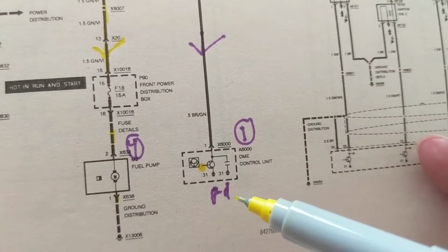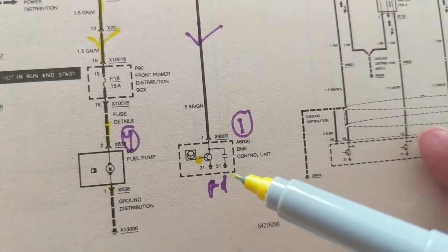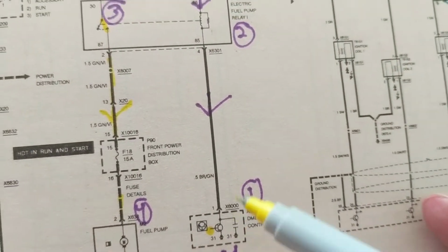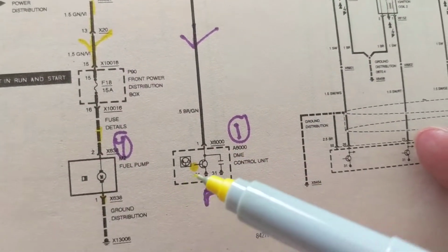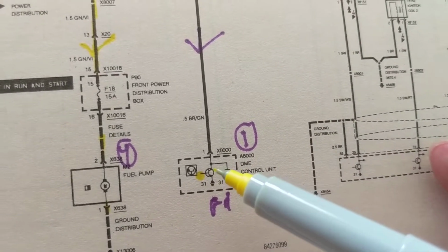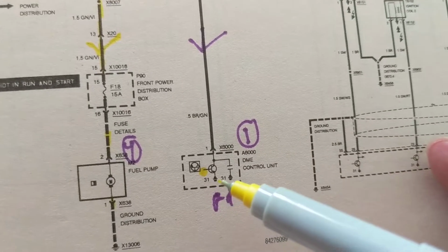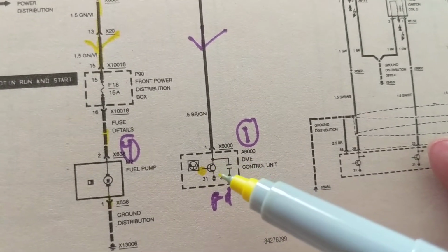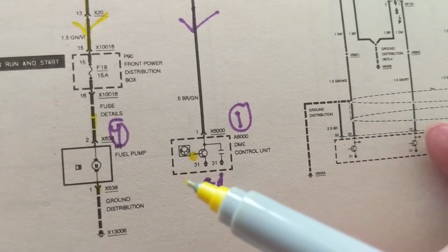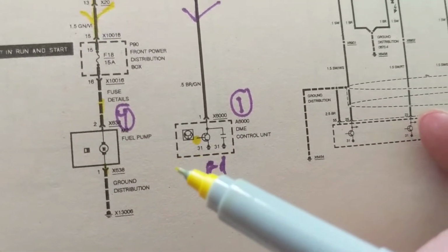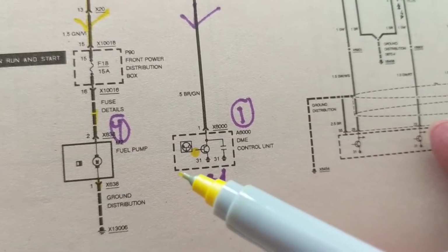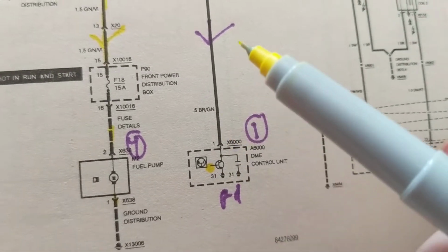Well, off the top of your head, you say something must be controlling this, and this must be controlling something else. Exactly. The computer is controlling this transistor to be used as an on and off switch. How do I know that? I look at the symbol, how it's connected. The computer, called the PCM or ECM, either abbreviation, either function, when you turn on the ignition switch, it knows, hey, I have to turn on the fuel pump.